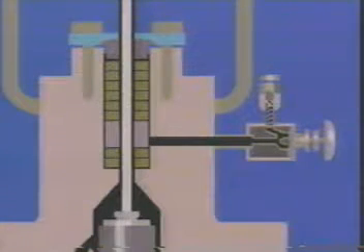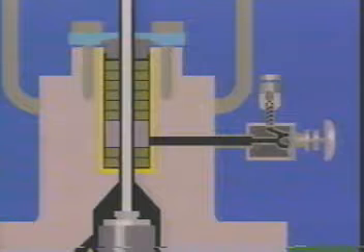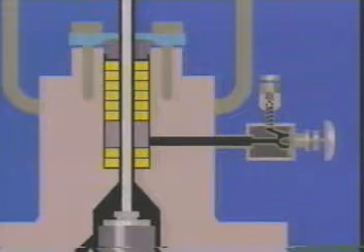Probably the most widely used design is the bolted packing box assembly. Trim components include the packing follower and the lantern ring. The stuffing box is a hollow, cylindrical cavity in the valve bonnet. Ring-shaped packing material is placed in the stuffing box and is compressed to fill the space between the valve stem and stuffing box wall. It provides the actual valve stem seal.